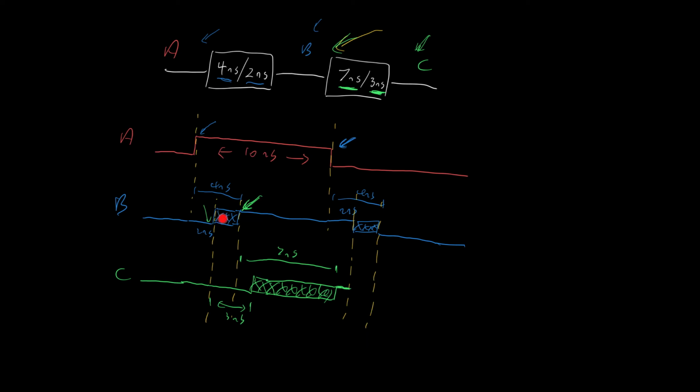Notice that in the first case, the period of unknown was simply 4 minus 2, and that's because the input transitioned instantaneously from one valid state to another valid state. For this one, if the input transitions immediately, then the period of being unknown at the output would be 4 nanoseconds, but we see here it's longer. And it's longer because its input has got a period of being unknown.